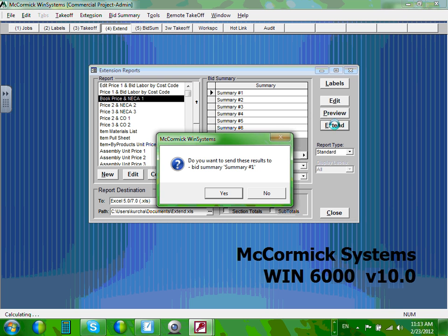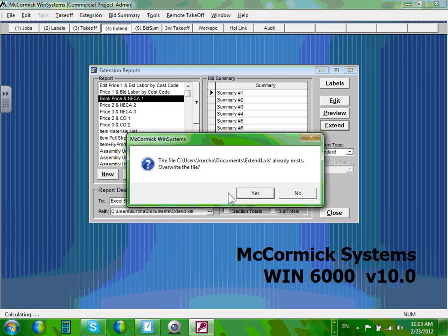Yep. Okay, what does this message mean? This says, now you did the takeoff. I have 2 values, Ashley. One value for the price of the material, and another value for the labor hours. No dollars for the labor yet. Total price, dollar value, and total hours, hour value. No dollar value for the labor yet. Okay? And they're asking you, do you really want to carry this into the bid extension, bid summary, so you can assign a labor and a profit and an overhead? Of course, we're going to say yes. If you don't, why would they ask you?